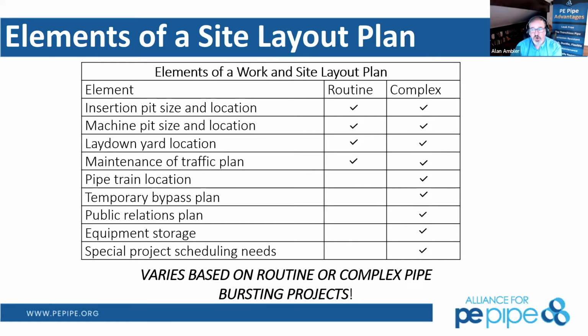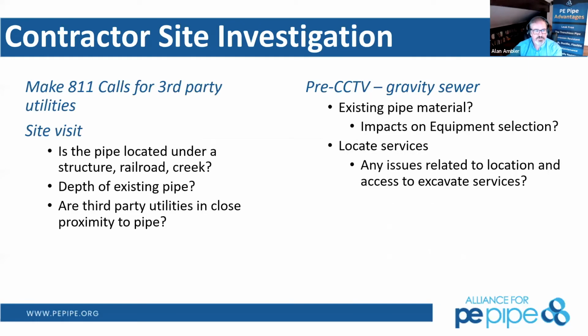So I often minimize design altogether on pipe bursting projects and then require the contractor to submit a bursting plan, which shows where their insertion pits or machine pits are going to be, as part of a shop drawing submittal. And then it shows that the contractor has in fact thought about the steps required to perform that pipe bursting project.